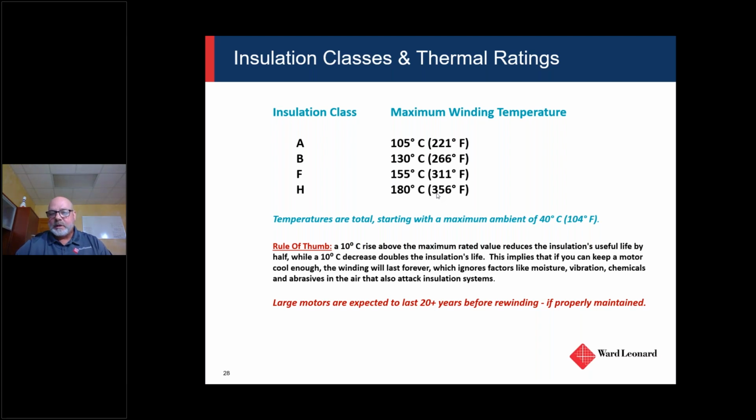So you can see the difference between F and H, especially down in Houston. If you're running full load, the motor is going to produce its own heat, and it's going to be shedding the heat, right? Then you add whatever the ambient temperature is to that, and in Southeast Texas, where we're at, it gets 100 degrees down here quite often. So you can definitely see where another 55 degrees, or 45 degrees, really helps. That's really why we use the Class H materials, right? It gives us a little bit more ability to operate in a very harsh and hot environment, right?